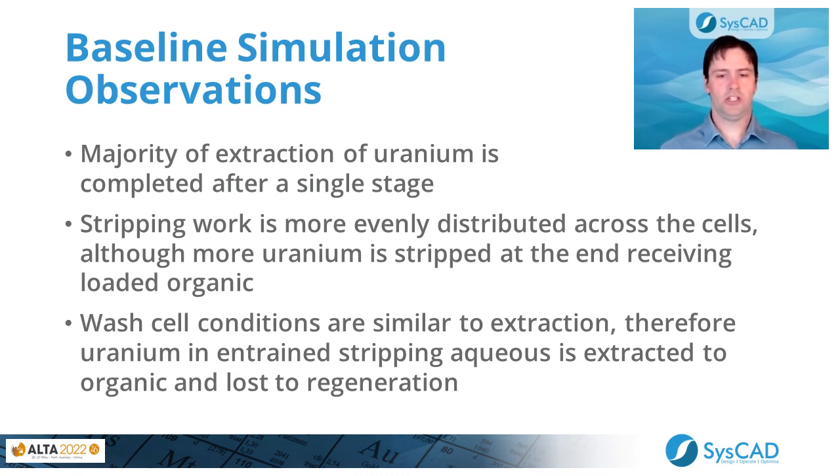As well, wash cell conditions, as I mentioned, are similar to extraction. Therefore, we could see a strong trend between entrained stripping aqueous and the amount of organic, or the entrained strip aqueous and the loss to regeneration. You saw a strong trend between the two.